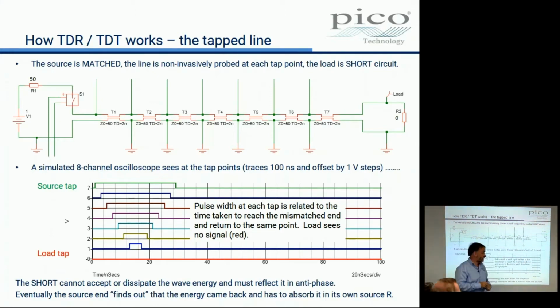Yeah, and I say this because we're going to be thinking with a VNA of relatively high frequencies traveling in cables and traveling in PCB lines, but even on the national grid, 50 hertz is a problem, as we'll see later. 50 hertz traveling along 100 kilometers of cable and coming to a short circuit does some really nasty things.